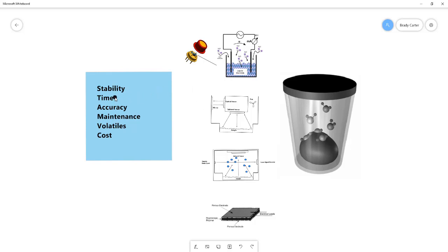In terms of analysis time, the thing that has to happen for a measurement to be taken, there are several steps. One is you have to reach vapor equilibrium, and for each sample type, there is a different amount of time that requires. High-fat samples take longer. Some samples can take less than 5 minutes. Once that vapor equilibrium is achieved, then you can take a measurement on the relative humidity and get the water activity, the equilibrium relative humidity.